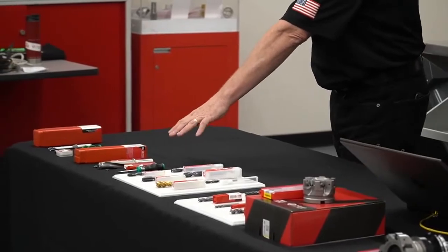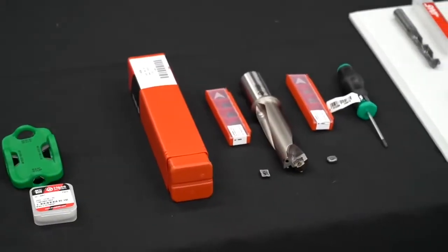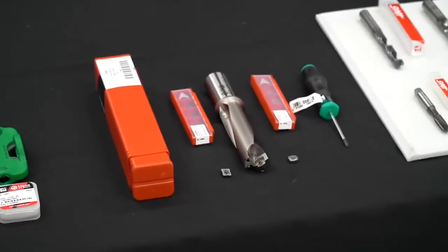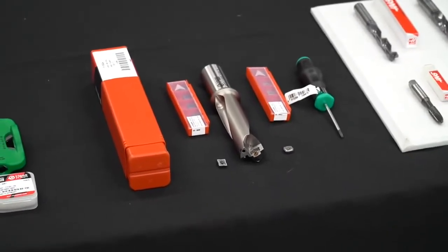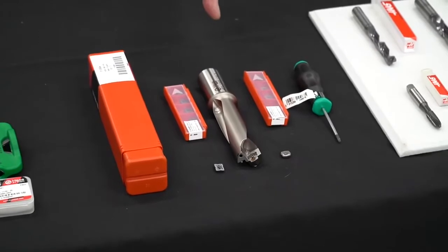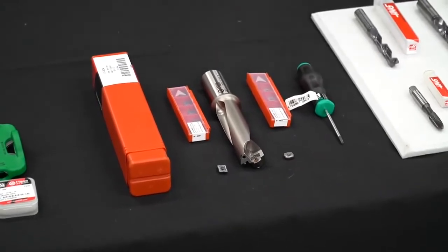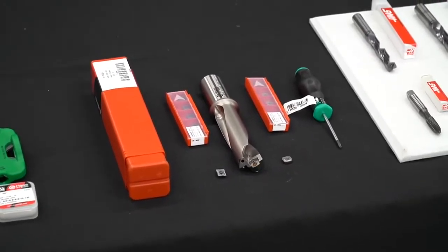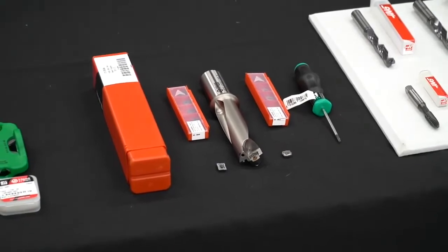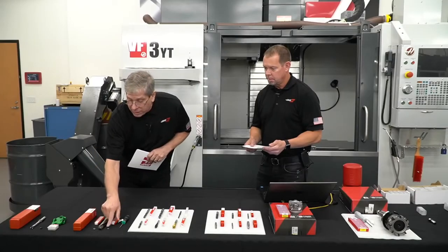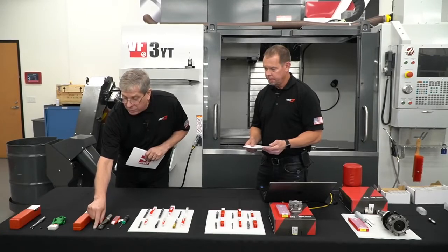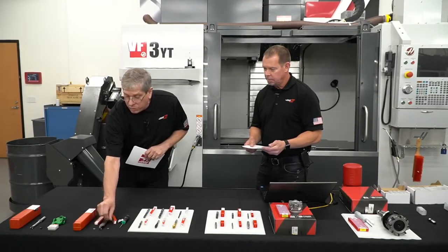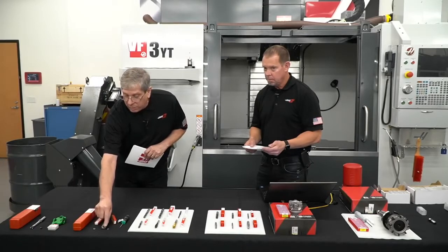Next we have the insert drills. These insert drills are for the medium and large diameter holes. We offer these in sizes from 3/4 of an inch up to 1 3/4 of an inch. All of these insert drills that we carry have two specific inserts that go in the drill. There's an inboard insert, or the internal insert. That's this one right here. This insert gets installed on the front, and then this insert is the periphery insert, which goes on the outside edge, or the bigger diameter.